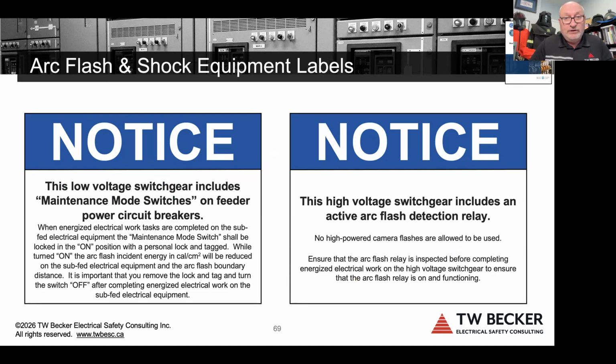When I've been in the field rolling out electrical safety programs, doing practical training in high and low voltage electrical rooms, again, arc resistant electrical equipment is becoming more common for high voltage and for low voltage. But I'm in there and the electricians haven't been trained on the new power system when it's a capital project. And for instance, a hospital's cutting over and they were not aware. So this would be put on by the responsible electrical engineer or indicated to put this on. And then everybody knows that it is arc resistant electrical equipment. The same thing when there's maintenance mode switches or arc flash relays.